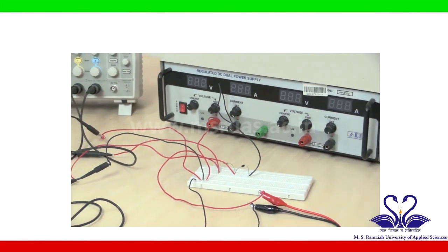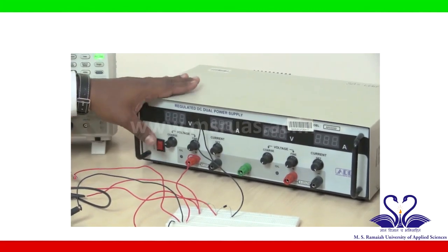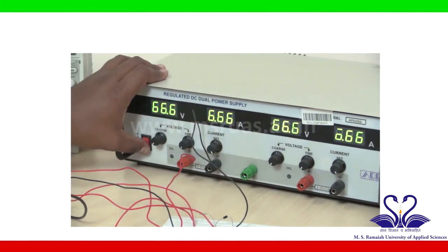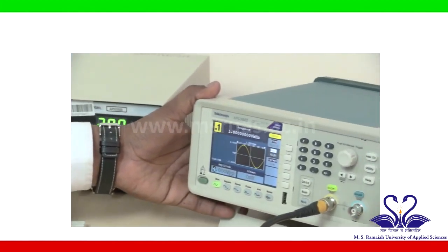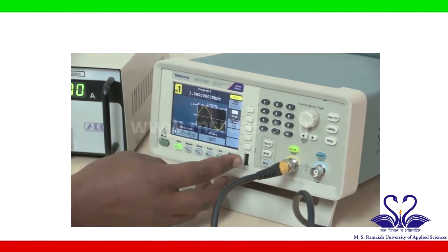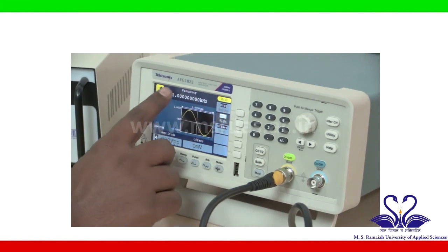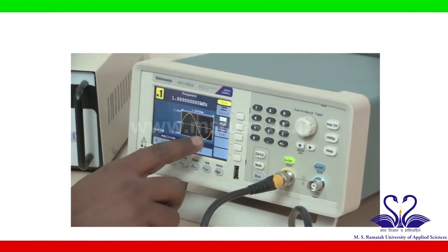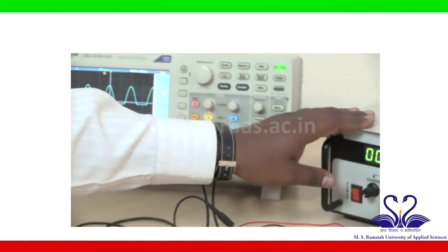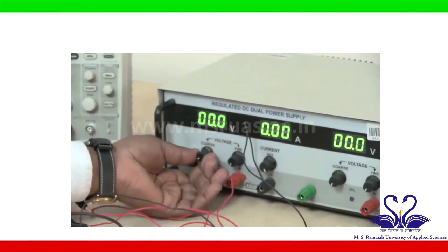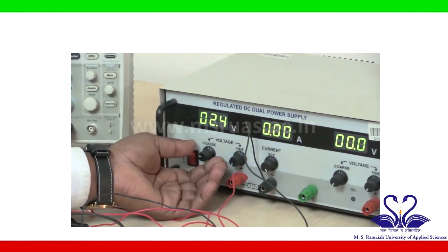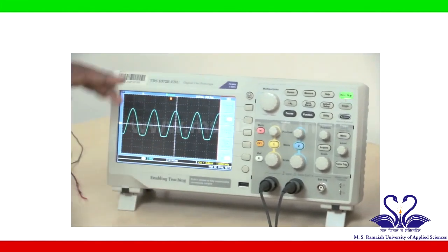Now again, before turning on the DC dual power supply, we will keep voltage at minimum value and current at maximum value, and turn it on. This is a function generator. For this circuit also we are applying a sine wave as the input voltage with a frequency of 1 kilohertz. Already it has been set as 1 kilohertz sine wave with 8 volt peak to peak signal, and we need to set the DC dual power supply as 2.4 volt, that I will vary from this knob. Let's make this 2.4 volt and come to the digital oscilloscope.